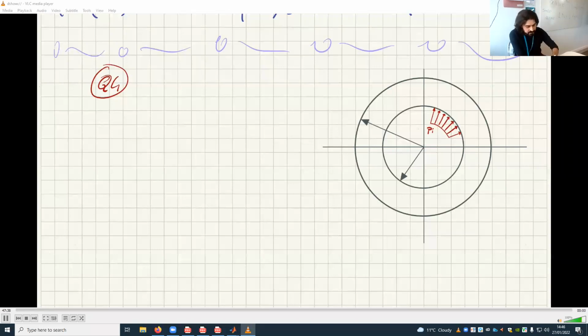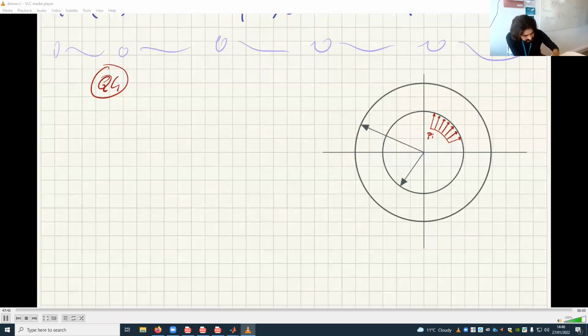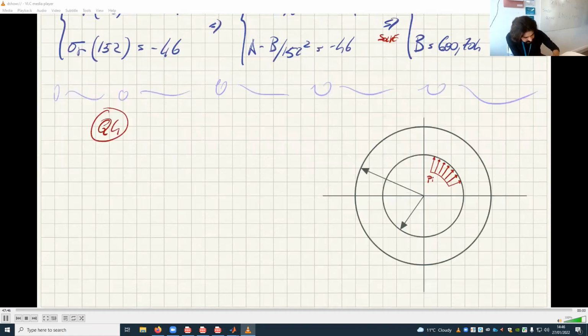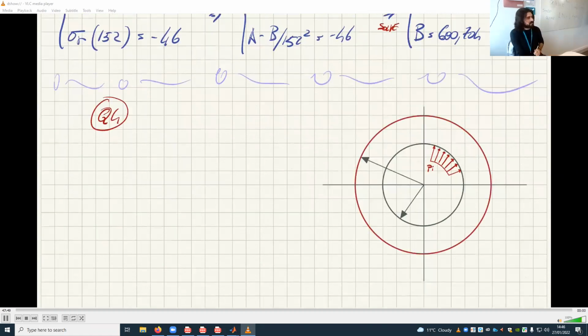The other thing that you know is that this outside surface that I'm selecting and putting in red is constrained. It's fixedly supported. It's affixed to a wall. So it's like this cylinder here is encased in some sort of wall, so it can't expand. The outer surface can't expand. So what kind of boundary condition is that? How do you work out the boundary condition on that?